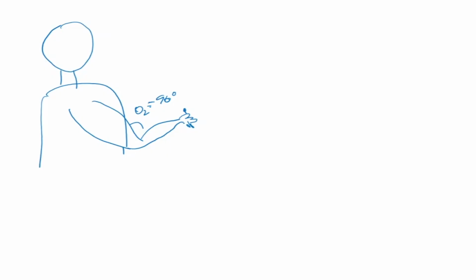Now if you think about it a little bit, when you're picking an object or placing it, or when you're writing, essentially all of us can do it in different ways, isn't it? Our hand has 7 degrees of freedom, so it basically means that there are infinite solutions. This is the redundant system, right? Because it is redundant, we can get infinite ways of doing a task, but all of us do it in the same way. When we are writing, we write in the same way. When you're picking up an object and keeping it somewhere, you're doing it exactly in the same way.